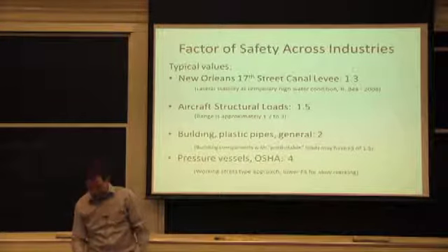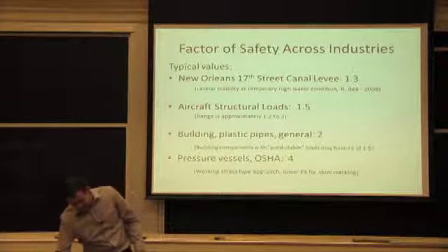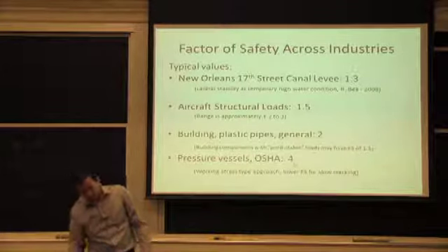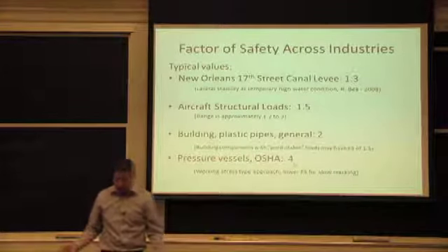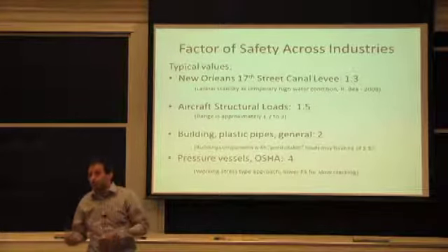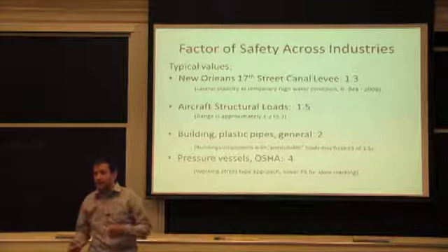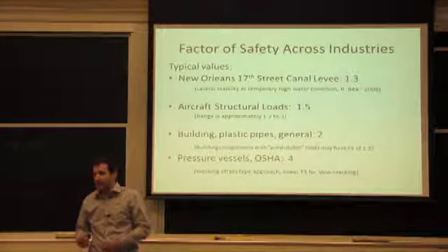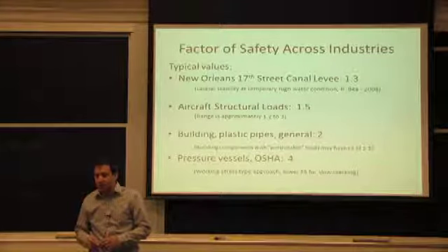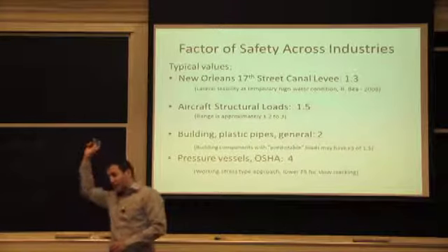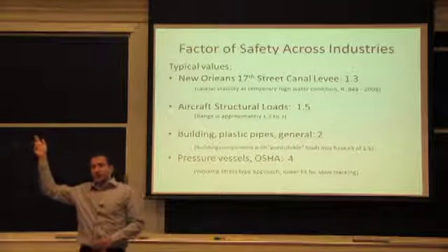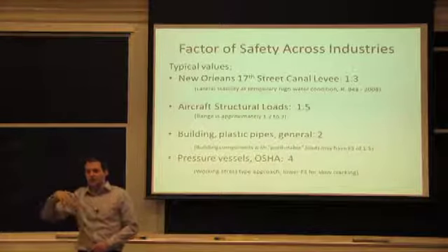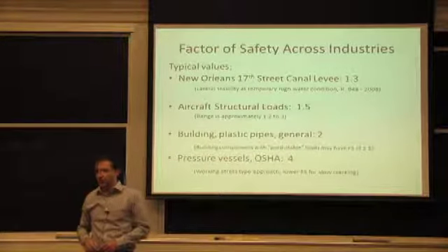And the one that I was hitting on the most was the safety factor for the pressure vessel, where I pointed out, well, you have water hammers, you have other loads, you have welds that come into the design, and they're not really accounted for. You don't need to say, oh, I'm going to have maybe a water hammer. Everybody can have it. So it's part of the code, and it's built into that factor of safety of 4.